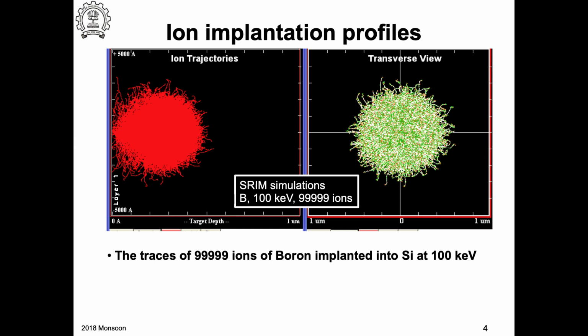So let's not go to such dramatic numbers. I would increase the doping to 10 raised to 18 per centimeter cube. Maybe it is needed to control the short channel effects or whatever. So what does it mean? In this channel of the MOSFET, you may have one dopant atom, period. One dopant atom. It may be there or may not be there. So then it becomes important to do this kind of simulation. The averaging does not work when your devices are really very small.